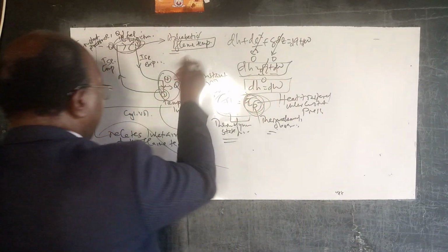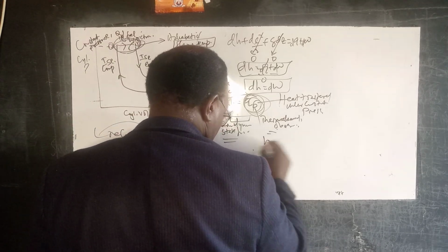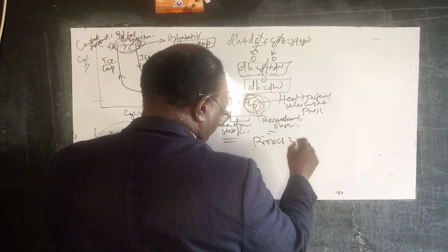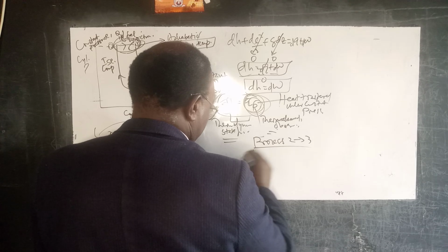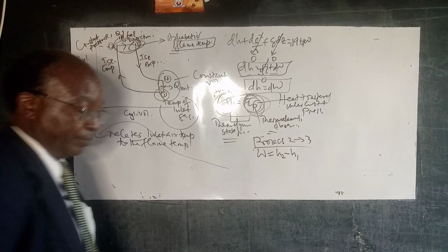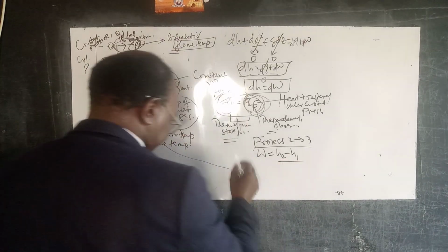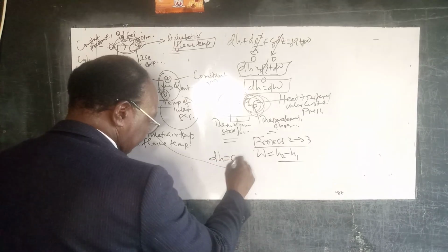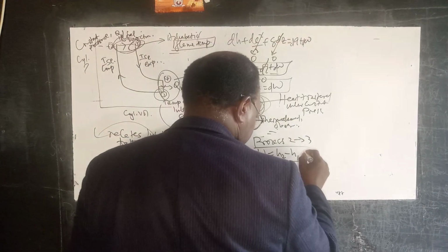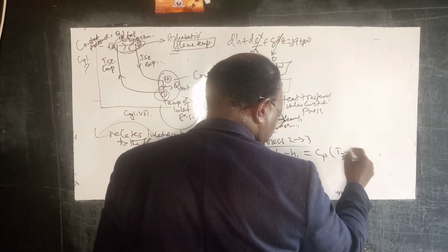So the work associated with that particular process, process 2 to 3, we have W equals H2 minus H1. And so, what is H2 minus H1? dH, we remember, is Cp dT. So, we can link that and say W is Cp times temperature 3 minus temperature 2.